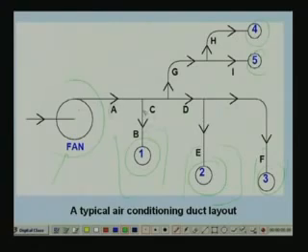These are the duct portion. So you can see that for this kind of a duct layout, you have the fan here, and the location of these outlets 1, 2, 3, 4, 5, etc. are fixed by the design of the building. Okay. And you also know from the location of the fan what is the distance, for example, from this point to this point. Okay. Similarly, from this point to this point. So physical location is known, so you know the distance, and once you know the distance, you know what is the length of the ducts. Okay. So normally the length of the ducts is known.